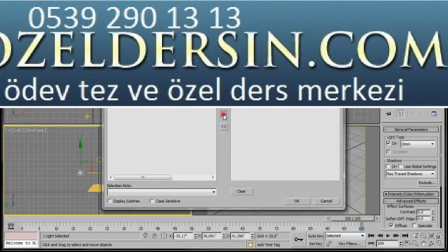So I'll click on my spotlight. I'll come over to area light parameters. And in the radius, I'm going to type in 15. And in the samples, U and V, I'll type in 8. Okay, now we can add some materials.